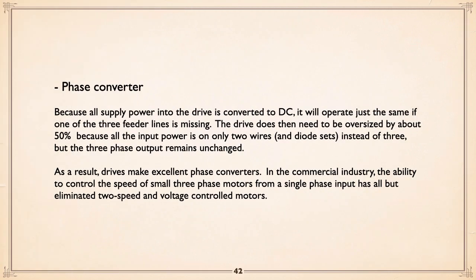Another little benefit, neat feature of, let's call them adjustable speed drives, that's what I'm used to. One of the nice things about these drives is you can use them as phase converters. The input is rectified to DC. The output is AC, a simulated AC.